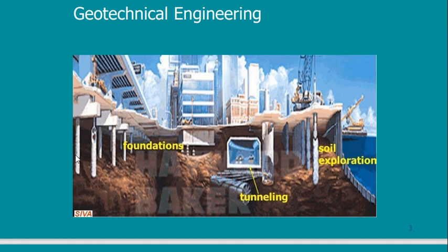So this is one thing. This building has a basement below the building. So this basement is below ground. It is affected by the ground, and it rests on soil. Is it the same soil as that below the bridge? No, it may be completely different. Even within the same building, there may be 2 types or 3 types of soil within the same location. So I need to know what are these types of soils.